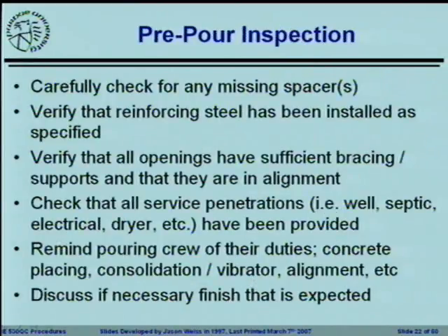All right, before the pour, you should actually have a checklist that either you or someone that's working with you is going down and checking. They're checking for any spacers that are holding up reinforcing bars, any spacers that are holding blockouts, checking to make sure that the reinforcing steel has been installed. At the Armstrong Building, they had the opportunity to redo several of the pours in the footing because when they started to look for where the reinforcing should be in that particular building, they noticed that someone had neglected to put it in. Right? Reinforcing only works when it's inside of the concrete. All right? So you need to verify that the reinforcing steel has been placed.